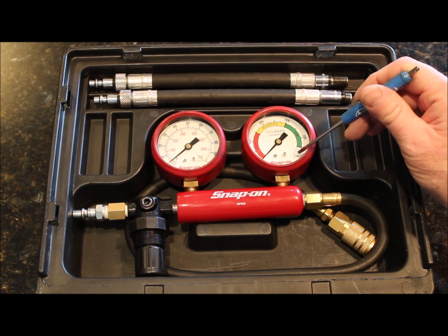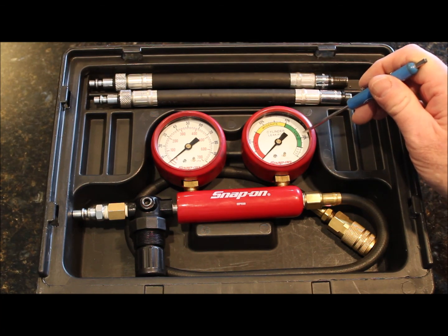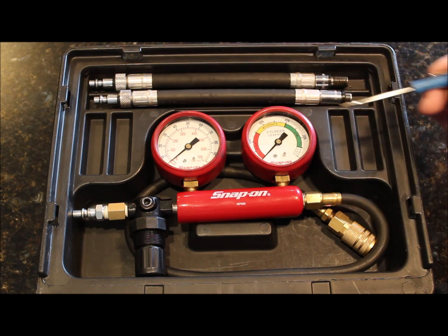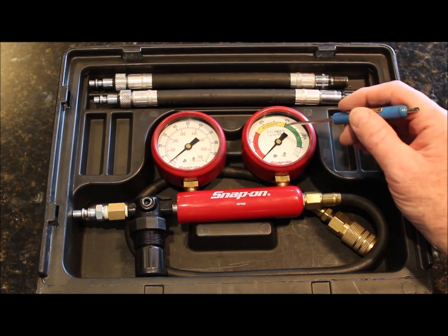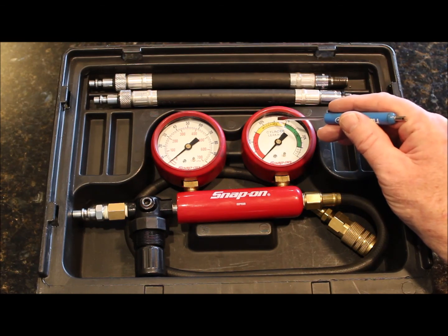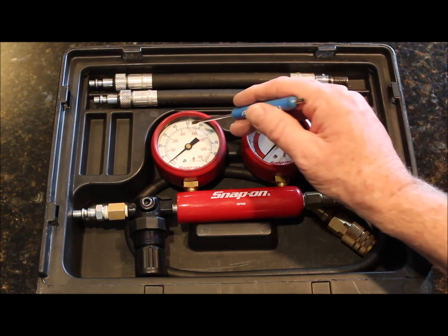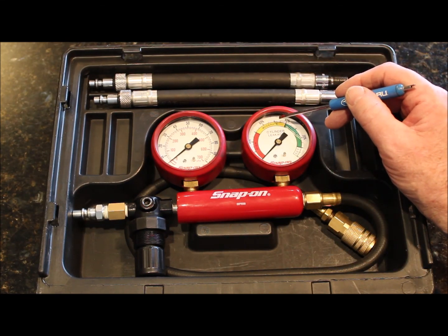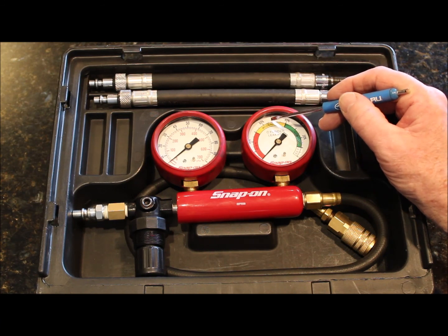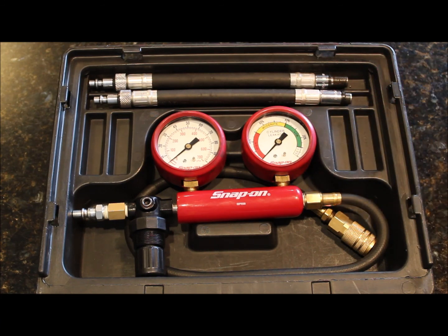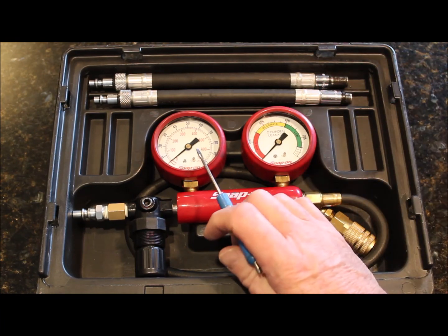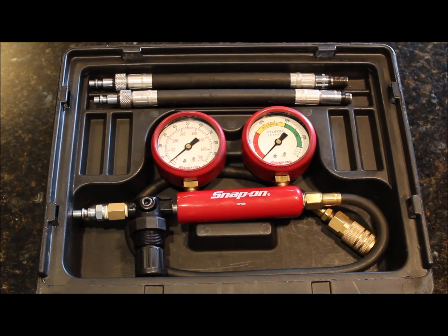We're at increments of 10. So this would be 0, that's 10, 20, 30, 40, 50, 60, 70, 80, 90, 100% leakage. So if I was at 50 for my input PSI, if both needles were pointing straight up, I have 0% leakage. If this was 5 pounds off, then I would say that's 10% leakage, 5 out of 50. So you wouldn't be able to go by these percentage numbers on the scale over here unless you're using 100 psi on the input side.